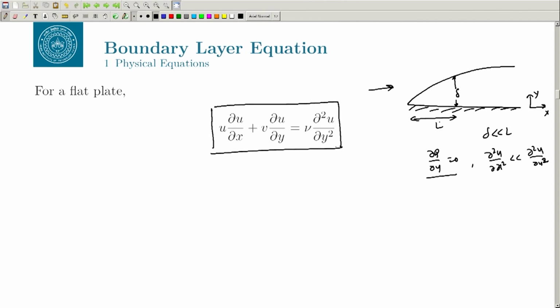We will look at the character of this boundary layer equation also. So, the boundary layer equation describes the flow. It is basically the ratio of the viscous force and the inertial force, the balance between these two forces. So, if the Reynolds number is very high, then the role of the viscous force is limited to a very small area. If the boundary layer Reynolds number is quite high, then you will have the boundary layer very close to this region.